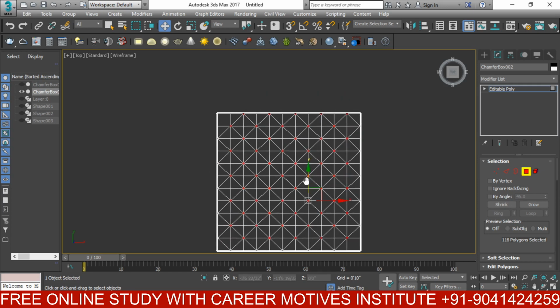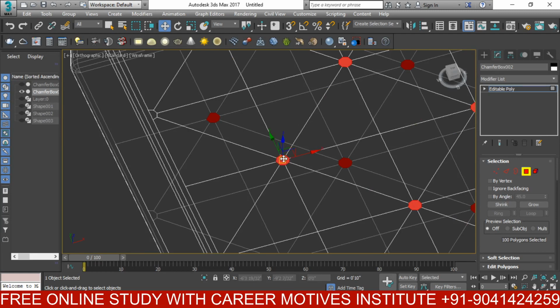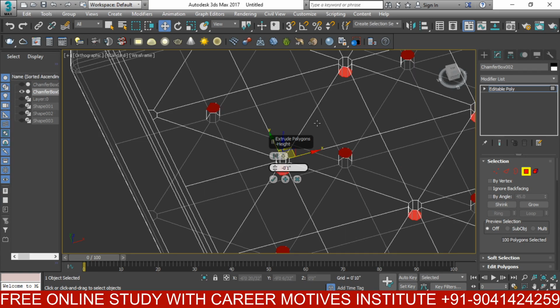Like this and this. Okay, so the next step is I am going to extrude these circles. Again right click, then extrude. Okay, so I am going to extrude them in the negative direction. I am extruding them by -1 inch.